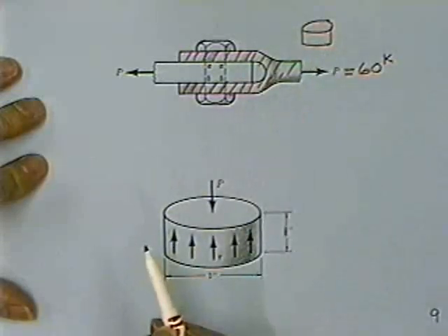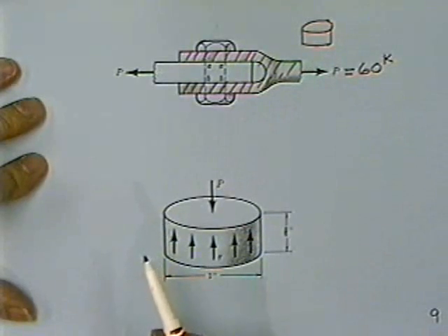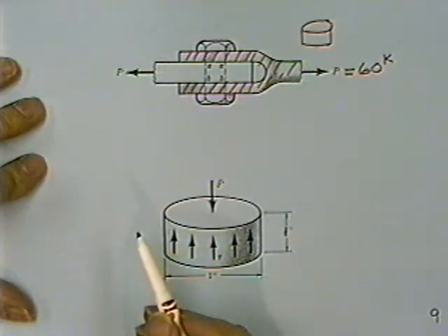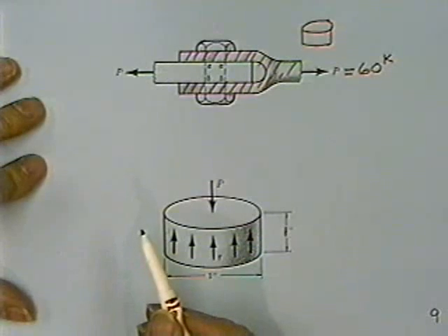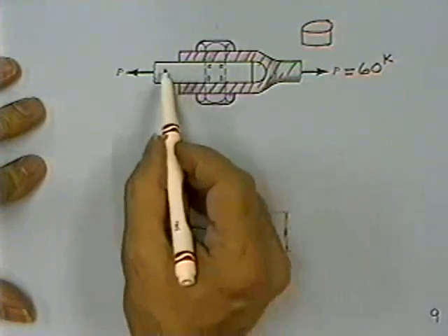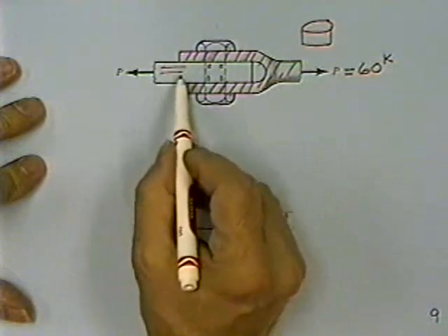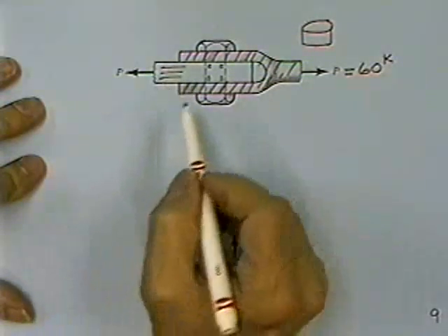And that's really how I recommend that you find the area in these equations. You look at it, you say, well, it hasn't failed, it's not going to fail, I'm not going to let it fail, that's how come I designed it so it won't fail. But unless you can see it failed, it's kind of hard to get the cross-sectional area necessary for use in the equation. So what you should do is you should assume that this left-hand piece of steel actually just pulled straight out and did fail.